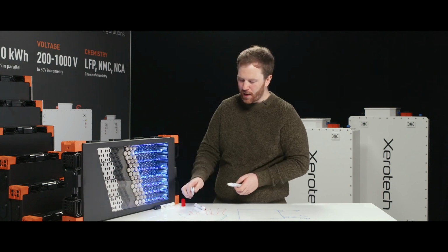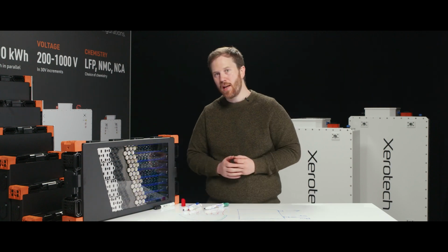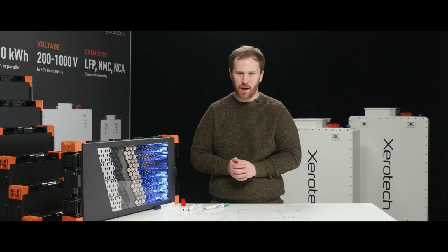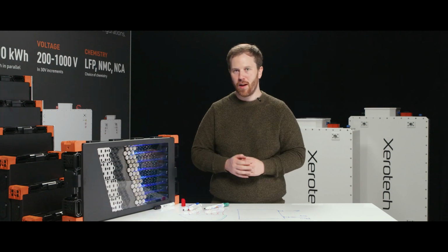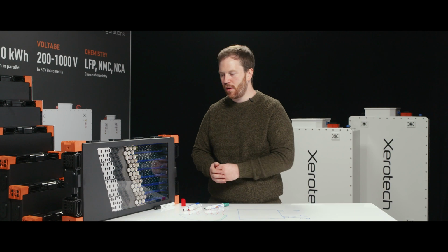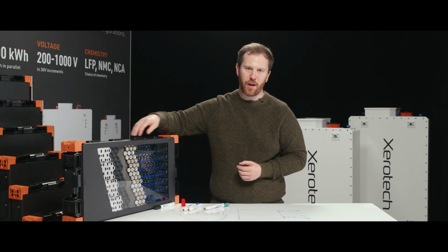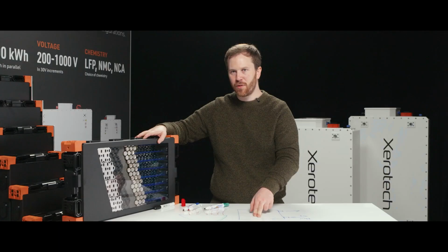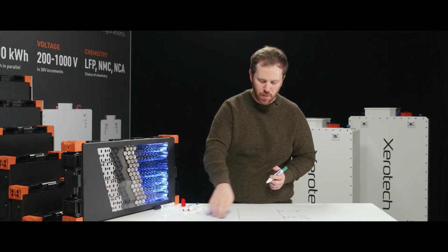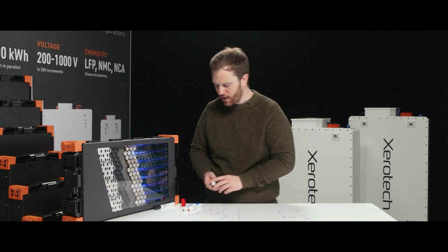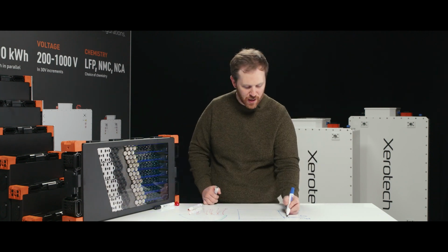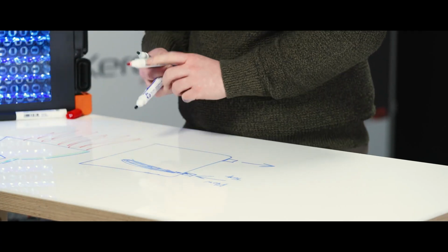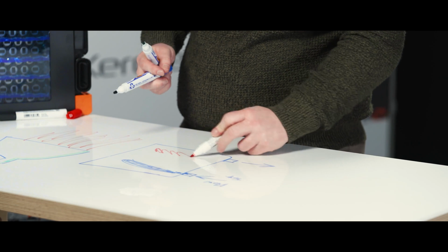And the challenge with battery pack designs, and it's a problem even today, even some of the best engineers, the best pack manufacturers in the world have differing approaches to do this, and some are maybe good and some are not so good, is that you actually don't want to maximize heat transfer coefficients in a battery module because it results in massive temperature gradients. So if we had an extremely high heat transfer coefficient in our pack, what that would mean is if we sent in cold water here, this half of the pack is going to be freezing cold, and this half of the pack is going to be much hotter.